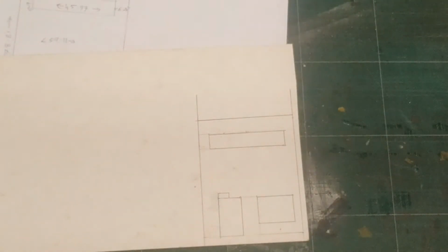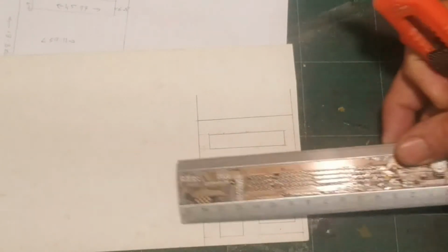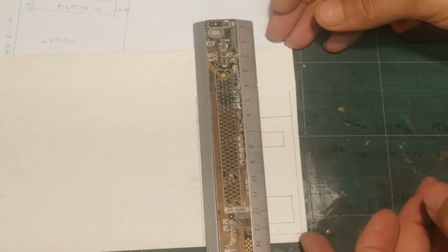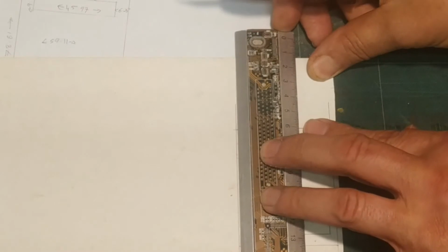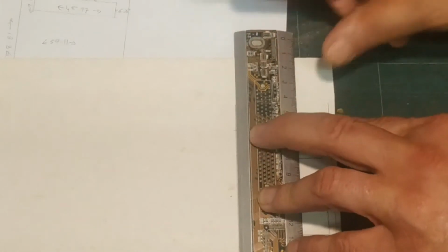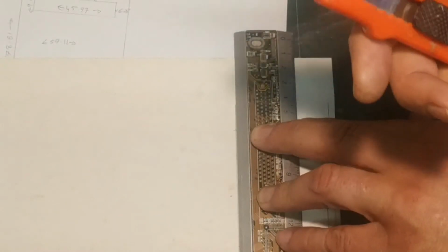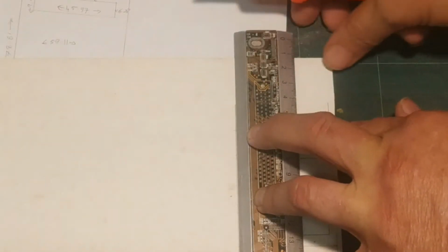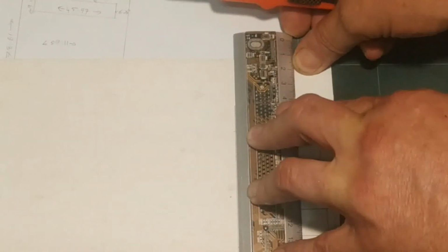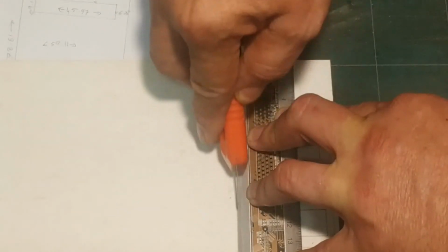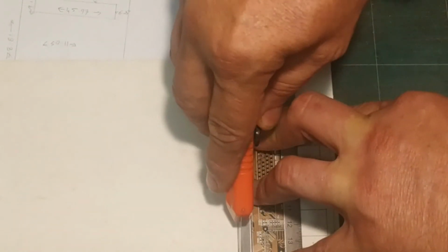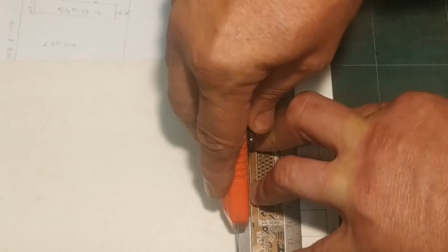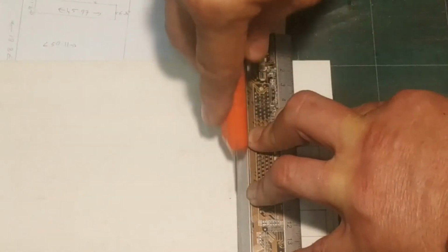Cutting is not a difficult job, but you need to be careful, and many light cuts work wonders instead of trying to force it through with one heavy cut. So I'm just using a hobby knife, one of these with the snap-off blades, which is quite heavy. Let me see that my line is lined up nicely to the little steel ruler, and then I start by making many light cuts until I have eventually cut right through the cardstock that I'm using for this specific build.